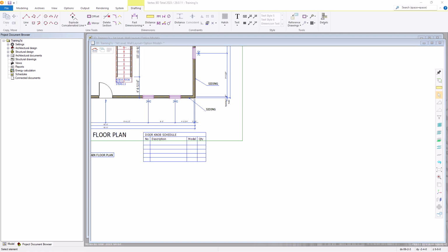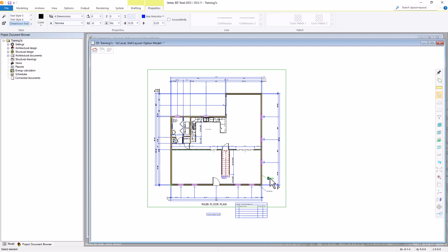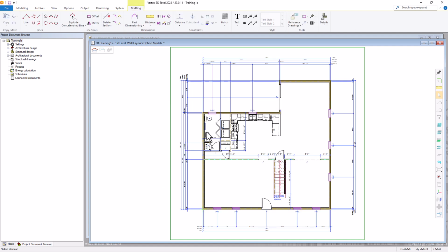Before we go with the Rooms tool in BD, I'm going to remove the text and table that we recently added, just to avoid any confusion with the room labels that we'll be adding. I'll select that text. I'm keeping my finger on the Control key and removing that kitchen note as well, and hit delete. I'll do Shift A to zoom extents and hit save.